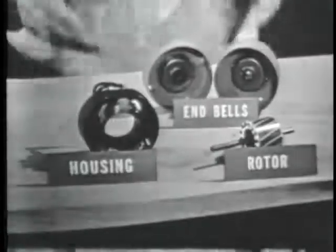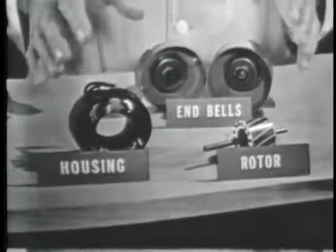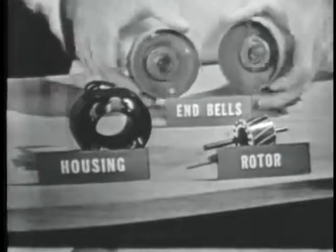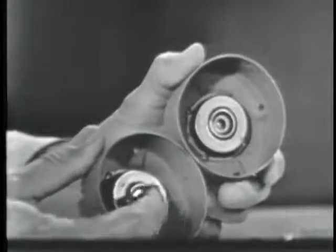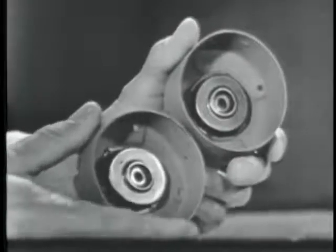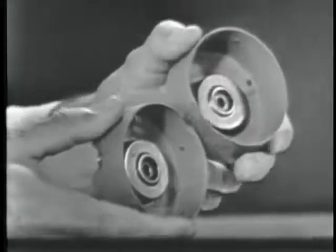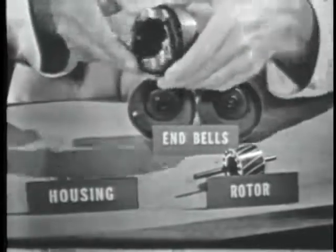Okay. This is a typical induction motor disassembled. Now, as we've said, it's very, very simple. We have the 2 end bells, the stator field windings, and the rotor. Now, let's take a look at these end bells. The end bells are used to house the bearings or the mounting devices that hold the rotor shaft in place. Now, notice there are no brushes or complicated brush holding devices at all. Just simply hold the bearings. And also inside the housing, or inside the end bells, we would find the housing that contains the stator field windings.